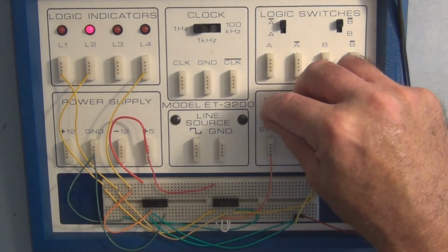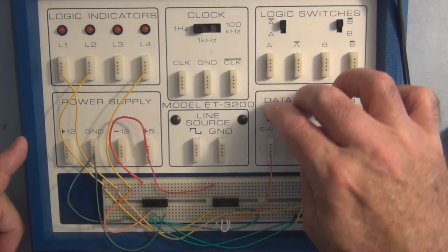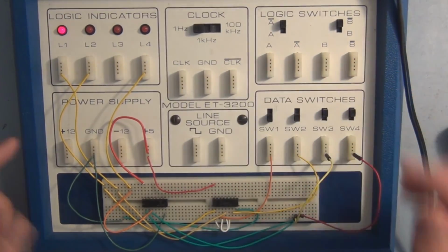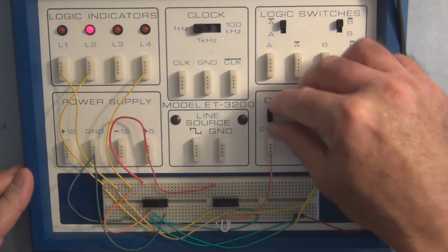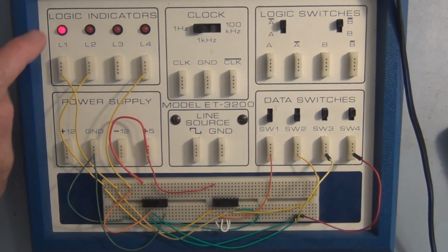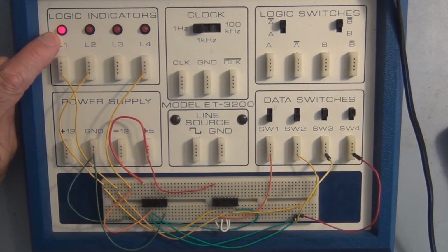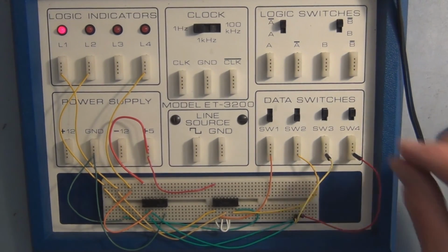So if we go ahead and put these, well, we get zeros, but if we go to 0, see what happens? I can't make these go simultaneously. One of these gets there quicker than the other, and that stronger one ends up getting set. So we have here in this particular case, the Q is a 1, and it's almost like tossing a coin.